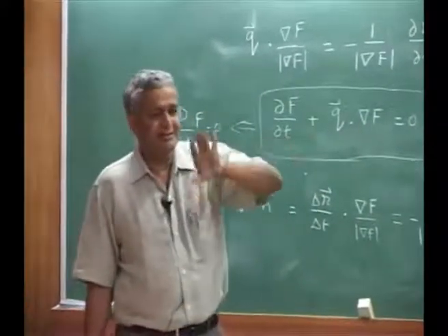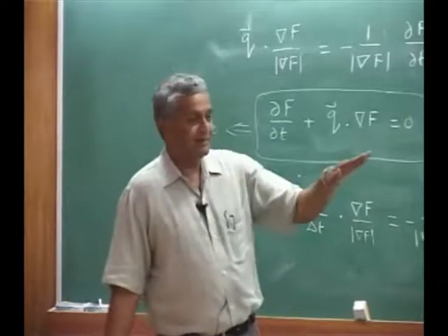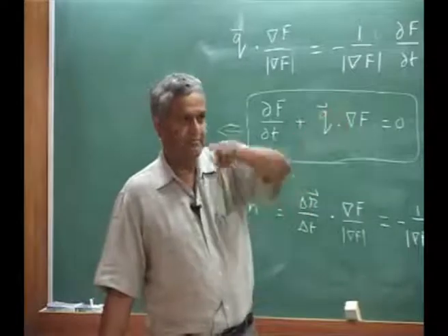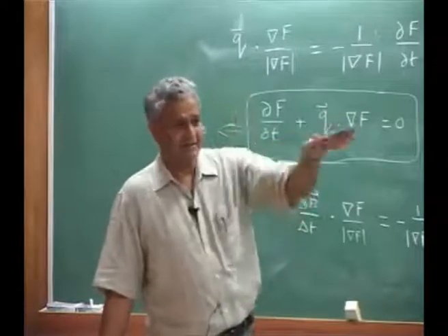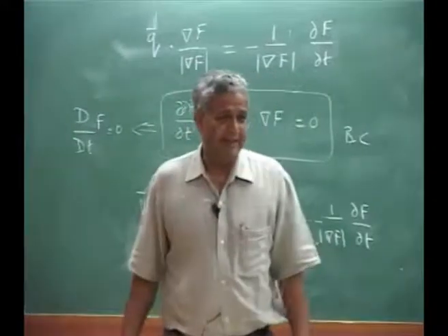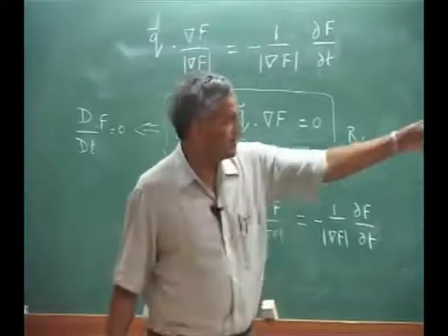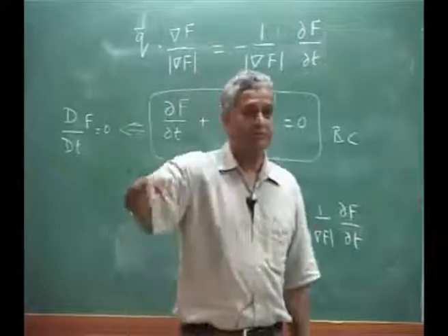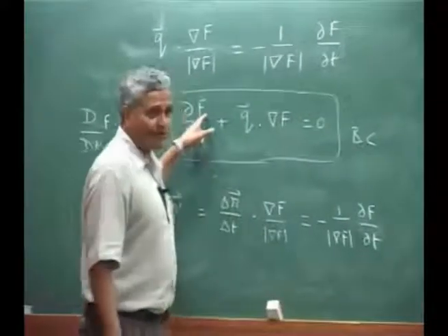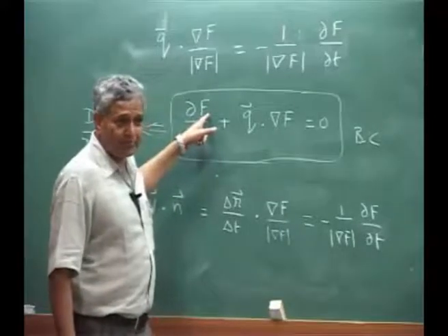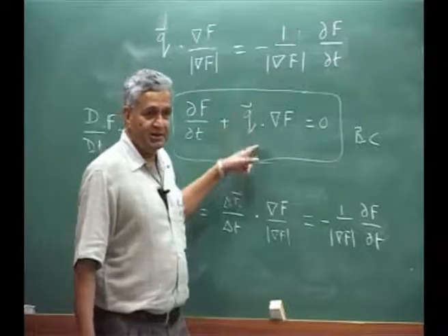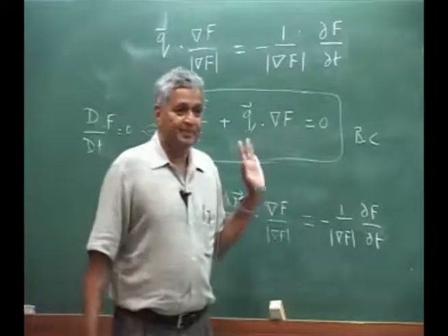An aerofoil we will take as a thin plate. And the plate you can write by an equation, because the surface is a straight line. You would normally take it as a plate equation, or if it is a 2D aerofoil, you draw a line. For that line, you can write your equation f of x and how it moves. Then you know the boundary condition, because you know how f is moving, and then you write the potential, and this should be satisfied.